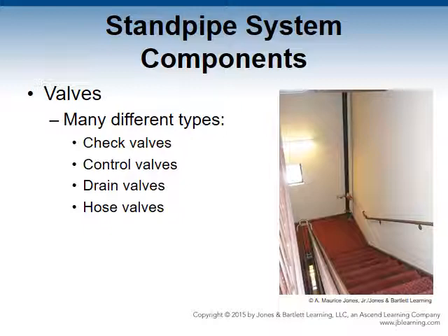Hose valves. They allow the fire department to connect to the water supply for manual firefighting efforts. These used to be located on the floor landing level, but now they must be installed on the intermediate levels unless otherwise required.